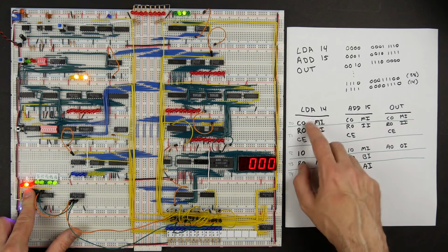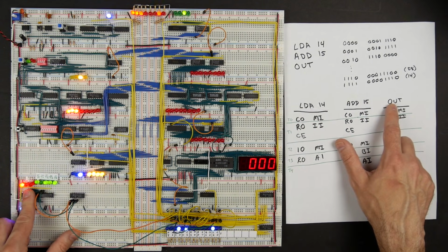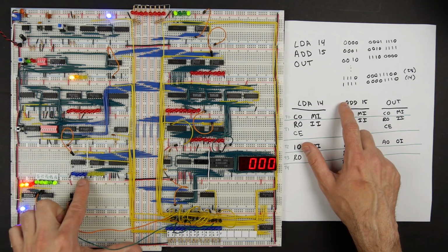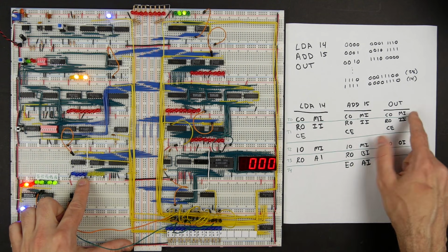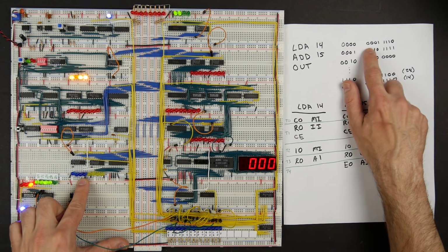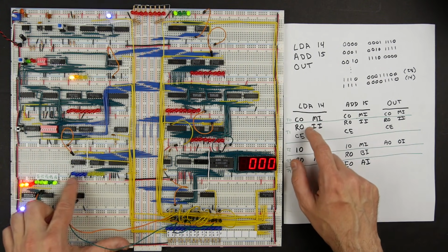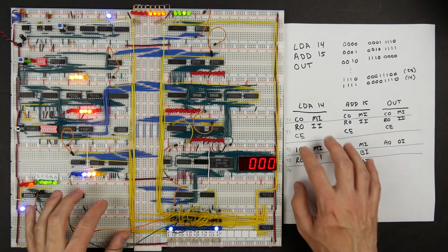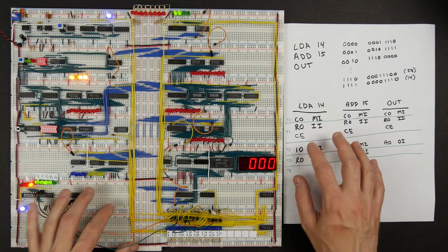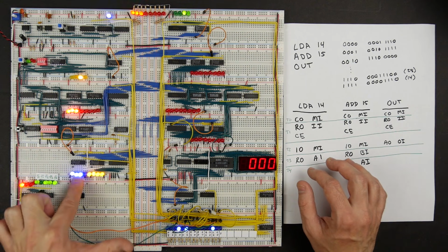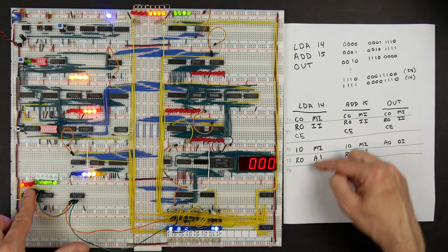But then the other piece of information, once we get into T2, T3, and T4, is going to be different based on which instruction we're actually executing. And so that piece of information is here in the instruction register, because by the time we get to T2, these first 2 steps will have loaded the appropriate instruction. So if the instruction is load A, that instruction is 0001, we'll have a 0001 sitting in the instruction register. So we have that information here. So all of the information we need in order to set all of the control signals appropriately is available in a combination of what's in the instruction register plus where we are in our count, so where we are in the actual instruction cycle.